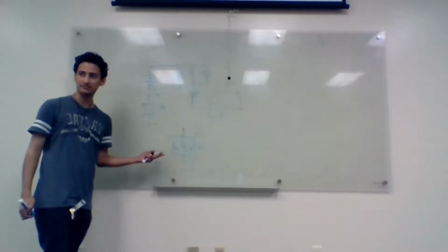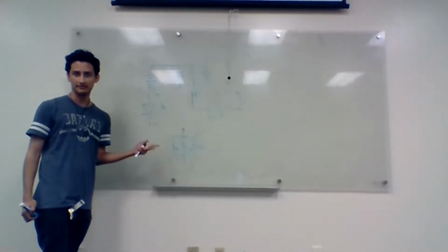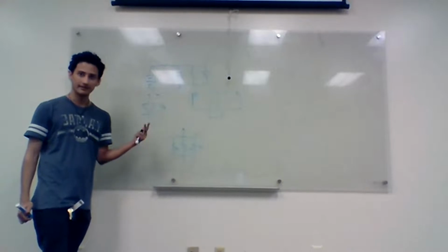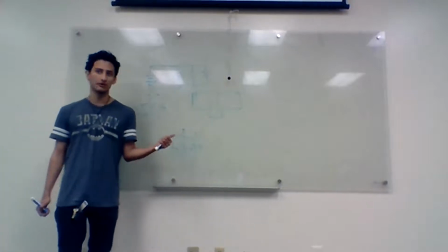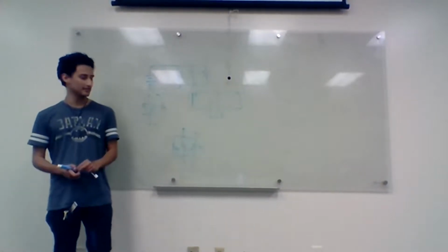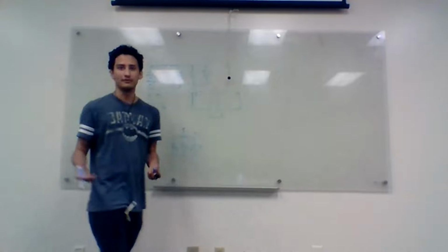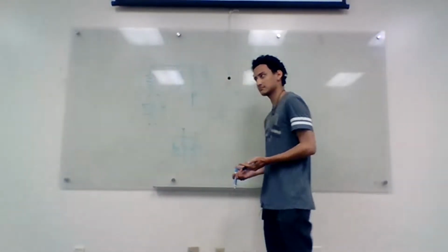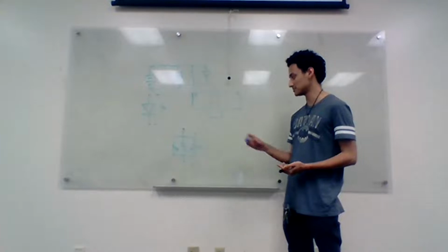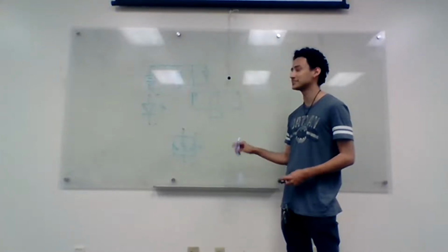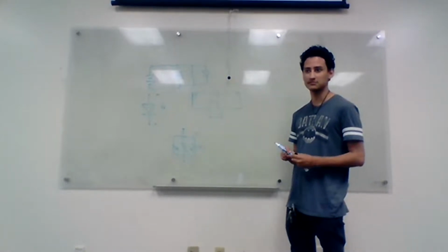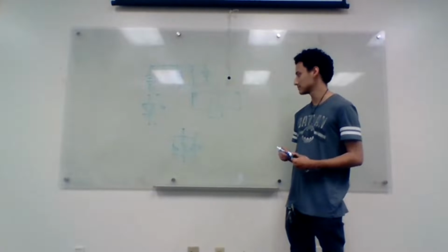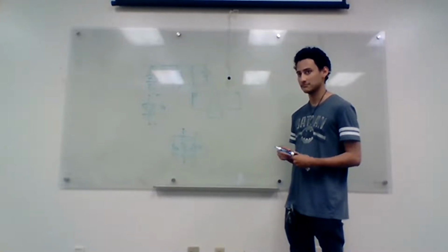those three values, C sub D, C sub J, R sub D, or G sub D. And of those three, C sub J is a physical thing. The other two are just based on forward bias. They're related to the small signal, which is the derivative of current for G sub D, and then the charge across the diode for C sub D. Okay.